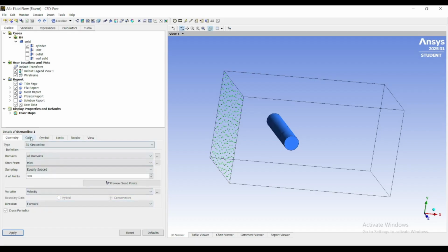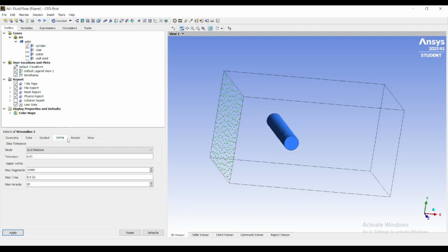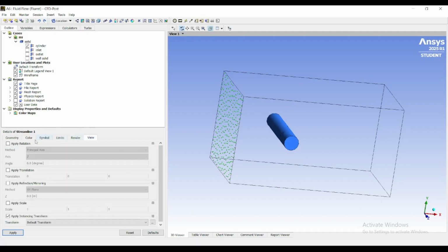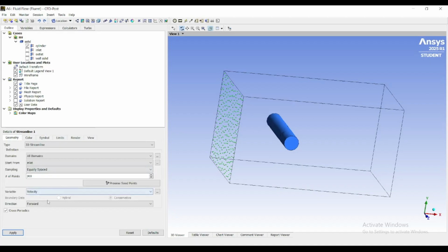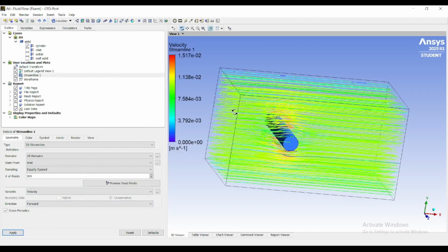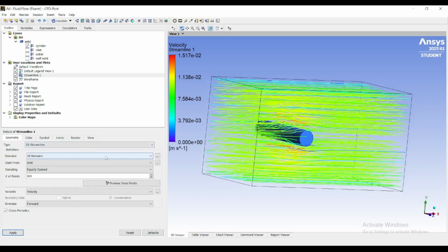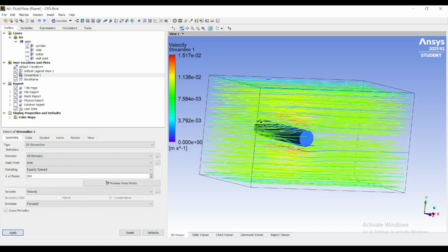Through contour plots and vector diagrams, Fluent allows you to clearly see these transitions, highlighting how turbulence intensity and flow regime affect performance and efficiency. For a deeper analytical visualization, Fluent's post-processing tools make it possible to examine every detail of the simulation. You can generate color-coded contour maps showing velocity magnitude, pressure, and vorticity to highlight areas of high flow activity.